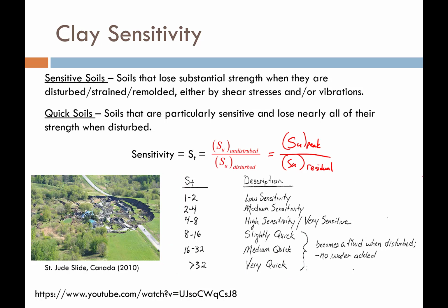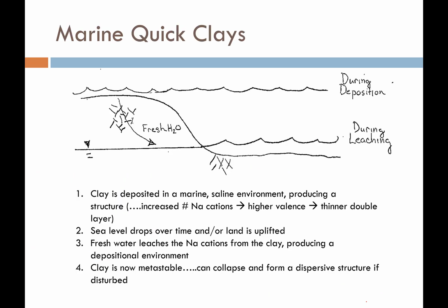Now in Scandinavia, they have some quick soils that have sensitivities greater than 50 and some even approaching 100. And so those can be very, very dangerous soils to build upon, and they need to be engineered by those that are familiar and experienced with those types of soils. If you guys want to see some cool stuff, check out this address here. This is a clip from the quick clays in Norway. It's from the Norwegian Geotechnical Institute. It's just a clip from a very old video about the Rissa landslide. But they do a nice little experiment and a demonstration that shows off what quick clays are, and it's pretty mind-blowing.